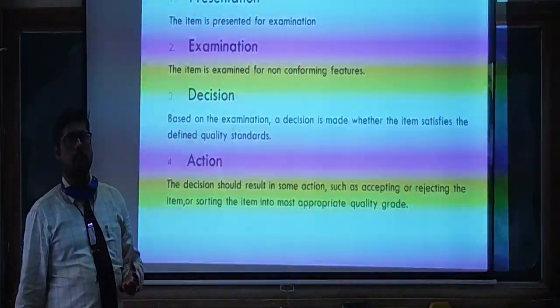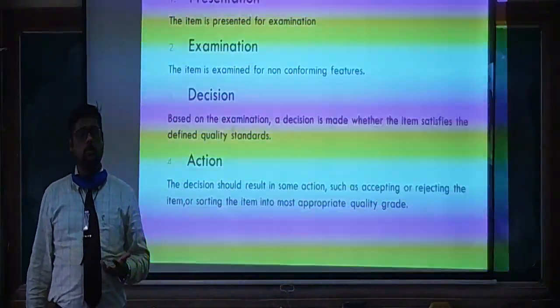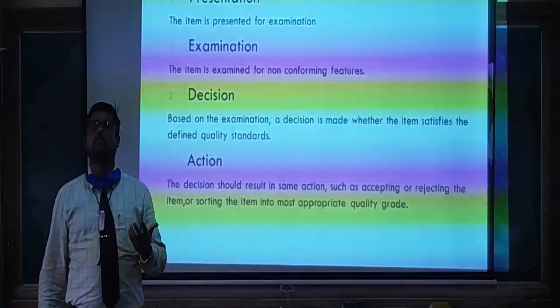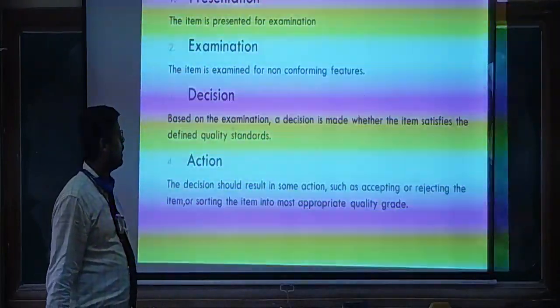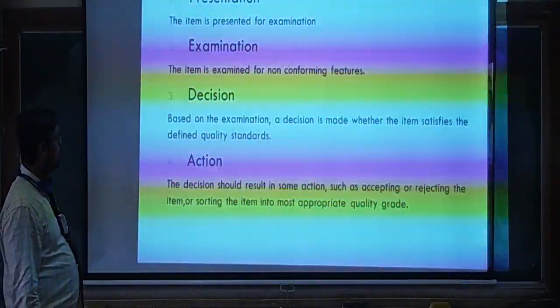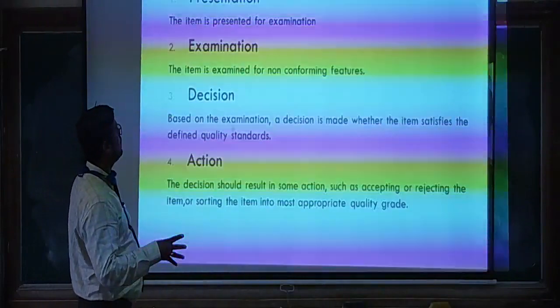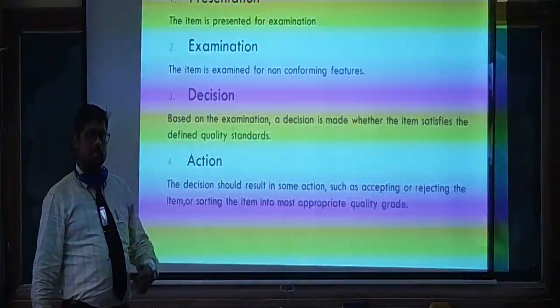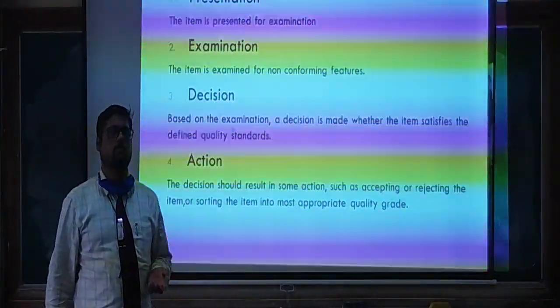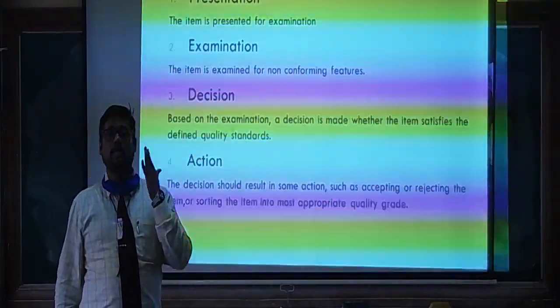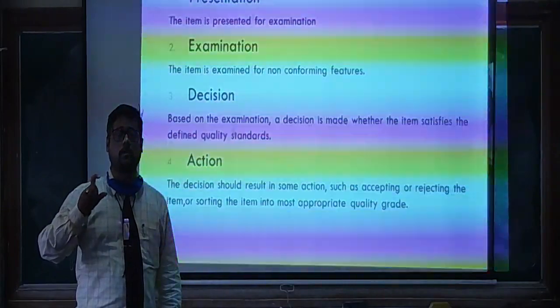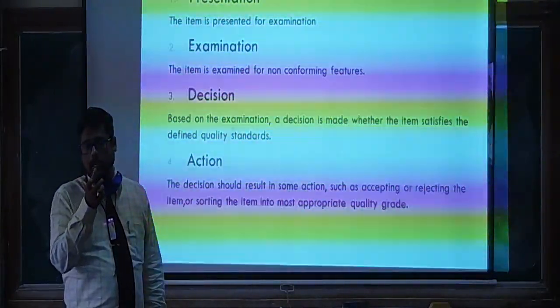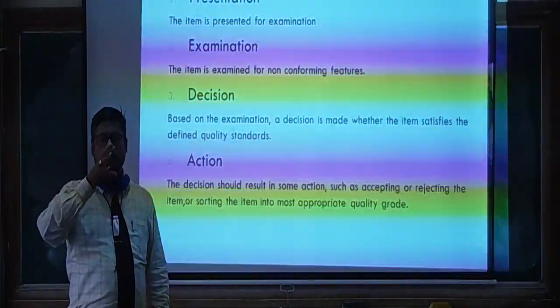Yes, we are checking either with visual inspection, or else using the Telesurf, we are checking that particular surface roughness feature. That is how we are examining that particular part. Or else, if it is a machined part, then we are checking the surface roughness values. The surface roughness for the roughing operation is different, the finishing operation is different, and the as cast is different. So it is specified in the drawing.